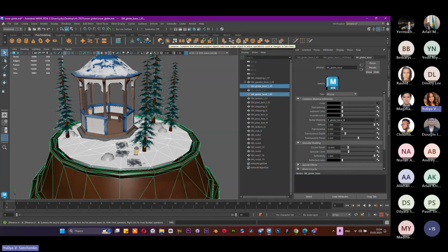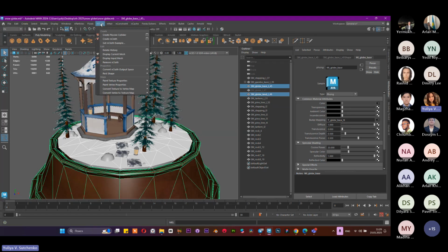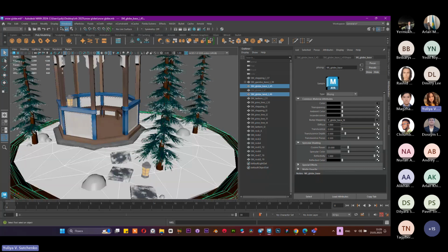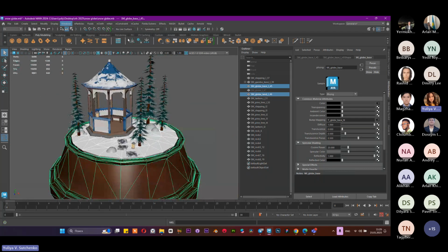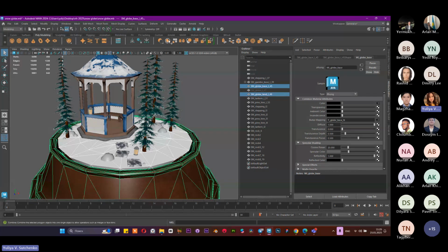This decreases the quantity of our passive colliders. For example, if we have a lot of objects and apply a passive collider to each of them, we have a lot of interactions, and it will also cost time for the simulation. That's why you should prepare your scene for the simulation. And that's why we are now in the modeling step, preparing all of these objects for the simulation.